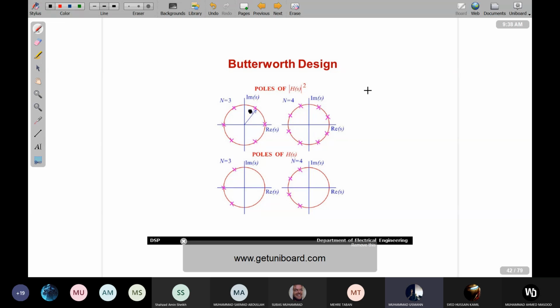यस सर. सो सपोज अगर मेरे पास n इज इक्वल टू 4 है तो इन दैट केस 2n हो जाएगा 8. सो H(s)H(-s) में आपके पास कितने पोल्स हो जाएंगे? 8 पोल्स हो जाएंगे. सो जो 8 पोल्स हैं उनकी लोकेशन क्या होनी चाहिए? 360. जो स्पेसिंग है उनके दरमियान वो है 360/8. ठीक है, सो मैंने इस तरह से पोल्स प्लेस कर दिए.